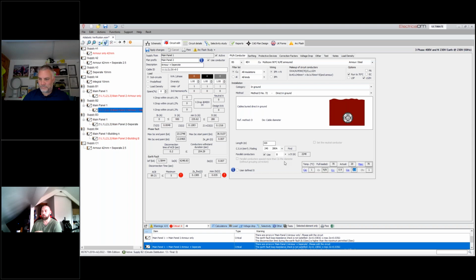So my two options for this would be either single core aluminium armoreds or a multi-core armored with a copper armor in there. And generally one of those two would usually, for something like this where I'm having to run such a long run as well, end up cheaper than doing a lot of groundwork for either a duct system or a trench or trough system that might need to go in there as well. And not to mention, when you put those in, you need drainage systems, and the groundwork costs can start to escalate quite quickly, depending on the situation and the location in the country as well.